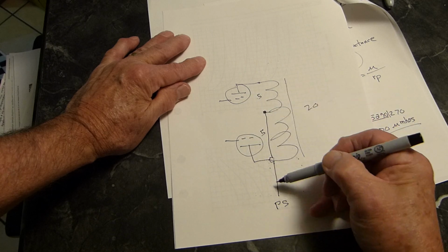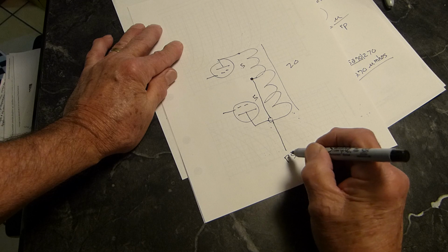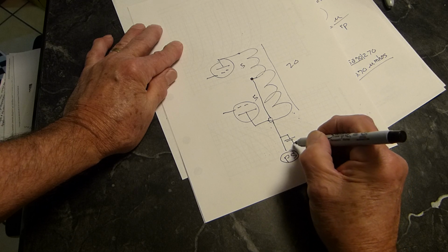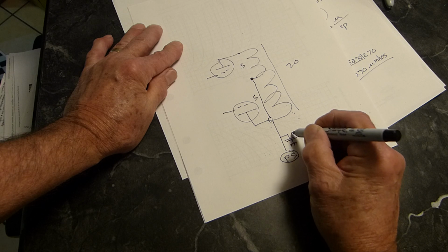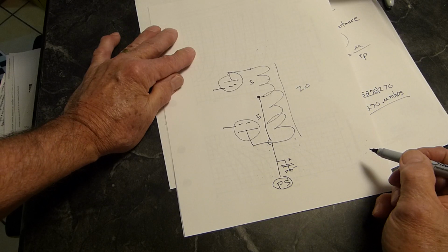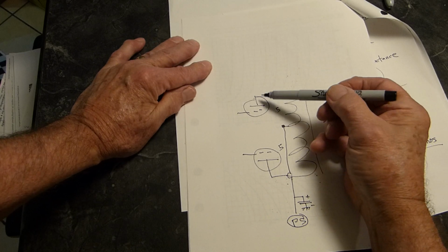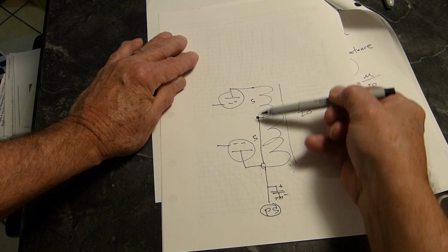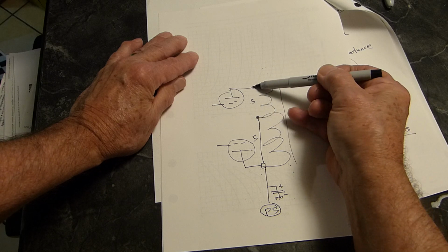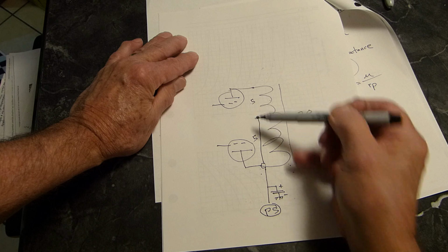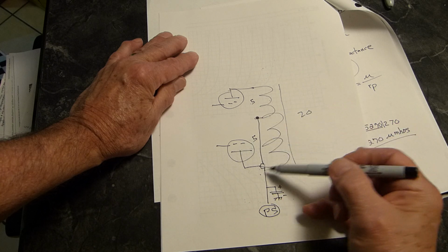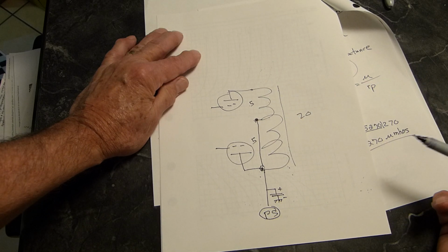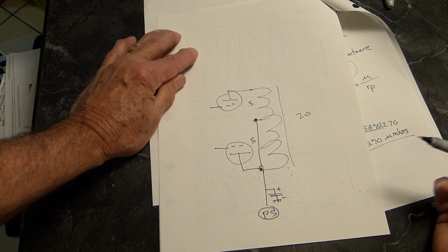This is at signal ground because what's the first thing that you're going to encounter when you get to the power supply? You're going to encounter that big electrolytic capacitor. So all of the audio that this tube is developing across this transformer is developed across here to here, from one side to the center tap, and then the other half is this tube from this side to the center tap. I apologize for my mess here, but I am not an artist, obviously.